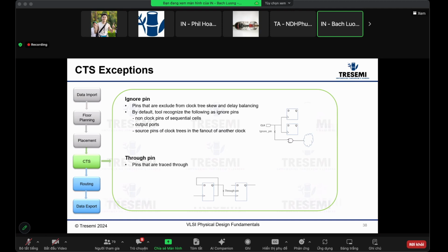Different kinds of designs will require different clock trees. For a CPU, central processing unit, which I'm working on, we normally just have one high clock speed. Other types of designs I used to work on, like telecom designs and some controllers, will have more clock trees and are a little more complex. They could have up to 20, 30 different clocks. Those are more challenging in terms of defining the different clock trees and their interactions, and they may have a lot of these exceptions.